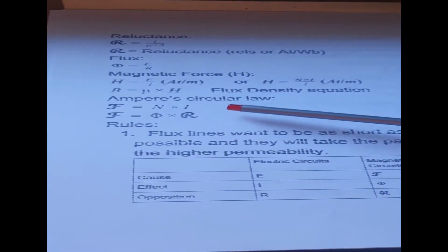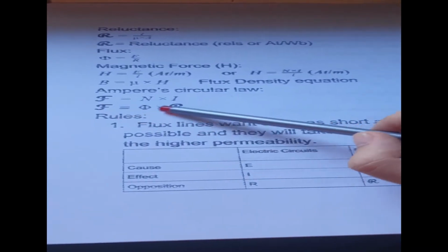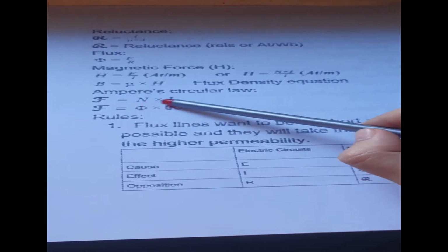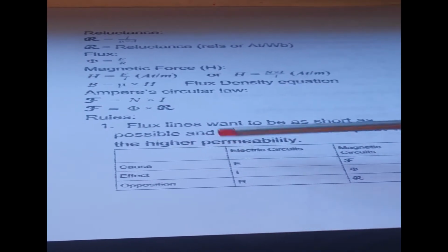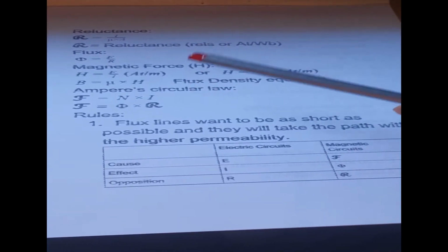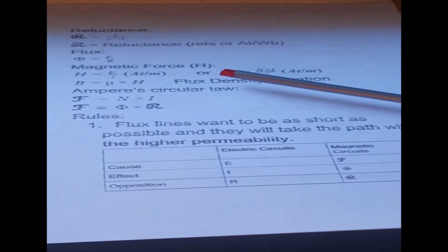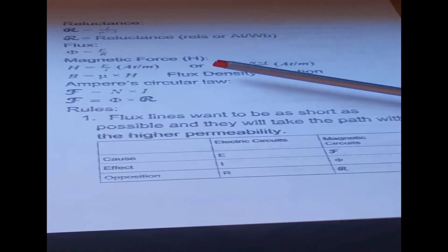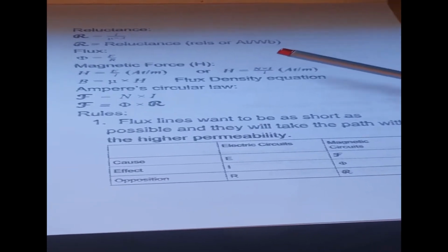Anyway, Ampere's circuital law, as I explained, is like Ohm's law when it comes to the MMF and its equation. MMF is basically the number of turns of the coil multiplied by the current going through it. I'm saying that with the current in the circuit, that's how you determine the power of the magnetic field, the magnetic force. Because realistically, in a circuit, it's easier to change the current than to make a system that adds turns to it or changes the metal.